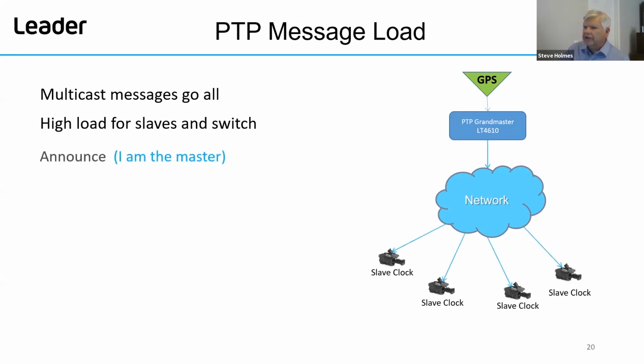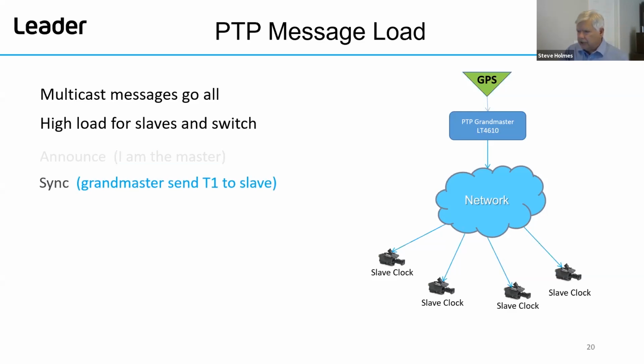So you're going to send out an announce message saying, I am the master, this is who I am, this is my IP address, this is my MAC address, this is my priority 1, my priority 2, my clock class. And that's going to go out to all the slaves that you can see down on the bottom. It will then send out its sync message, which is, hey, this is my time. All the receivers on the bottom see that.